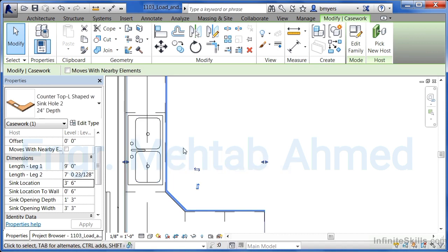This process that we just did is not just for such things as sinks. Pretty much anything that would be considered a component family would get placed in this way. There's nothing wrong with 2D if you only need to see it two-dimensional in that specific view. In the case of a plan view, if this is going to be the only spot I would ever see these sinks, then loading in two-dimensional sinks is fine because it'll show up and document appropriately. And finally, if we're going to place a three-dimensional sink into the plan, make sure to choose a three-dimensional sink and then shift it to place it in the appropriate location.